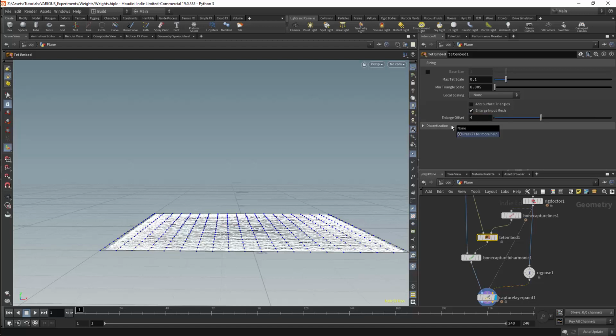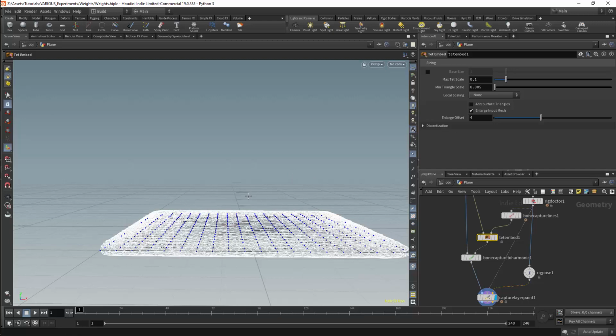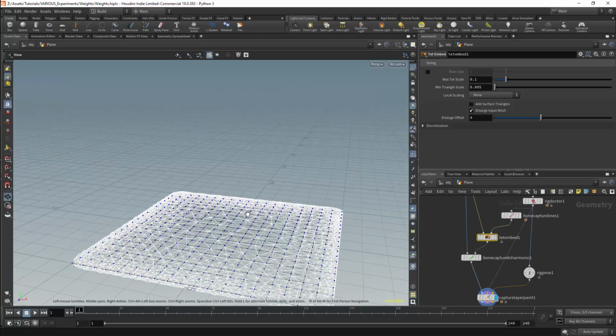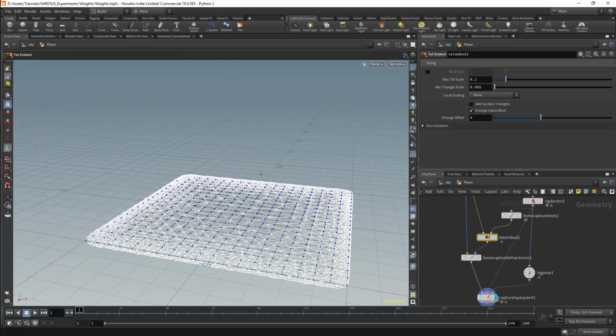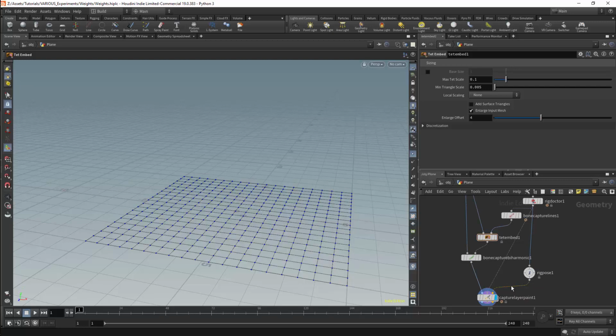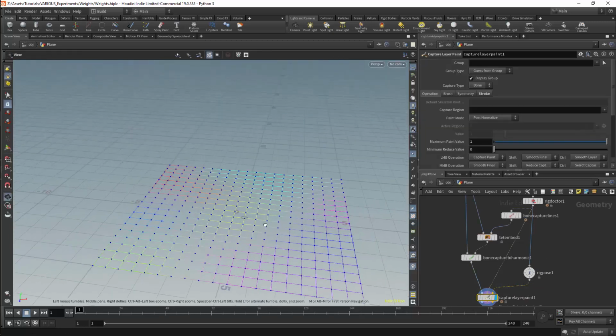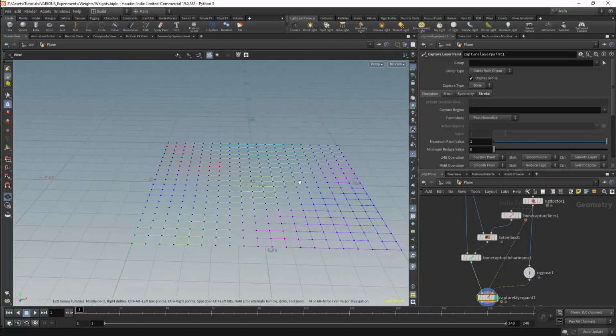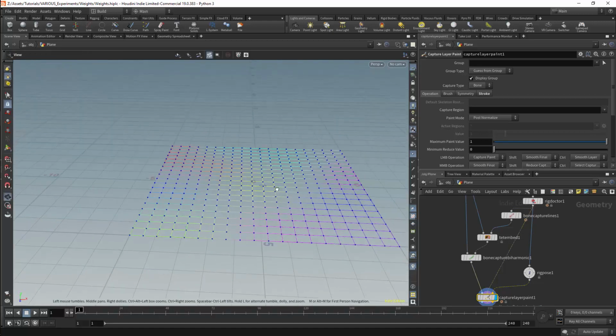This will be common if you, for example, have a bone-based rig for cloth, or for things like a bone-based facial rig. If the tetrahedral mesh is flat along the surface, no weights will be generated. The weight attribute will be transferred to the geometry, but all the weights will have a value of 0. So whenever we control a section of a surface with joints, we'll need to enlarge the tetrahedral mesh.